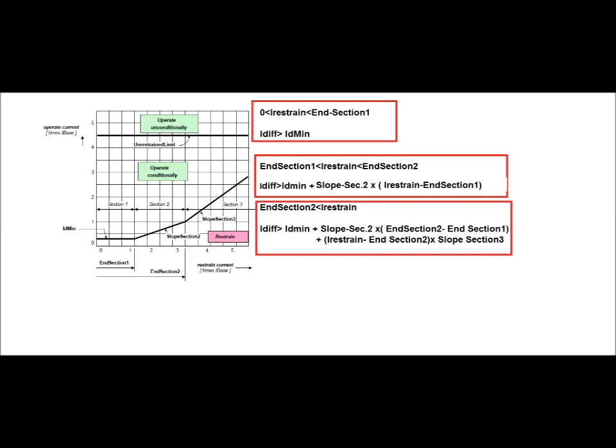These are the three boundaries of the RET670 characteristics. Again there is a setting of high set. If you give the percentage impedance of the transformer, it will automatically calculate the value of the high set. This is the characteristic of the RET670.